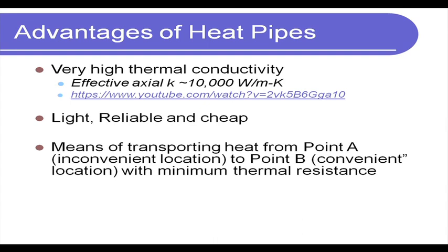Okay, but again keep in mind, this is not a heat removal device. Okay, it's a means of transporting heat. It's a heat exchange device, right? It's not a thermal solution. It's a means of transporting heat from point A to a point B with minimum thermal resistance, which is what we are trying to do in terms of waste heat recovery. If we think about it, what do we have? We have thermal energy due to some source which otherwise would have been wasted, and we want to extract whatever is possible from that source of thermal energy and utilize it somewhere else where it can be put to our benefit. And so heat pipe will enable us to do that very effectively.